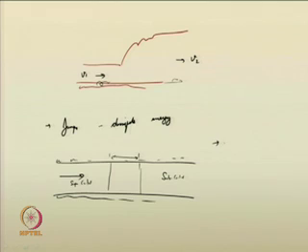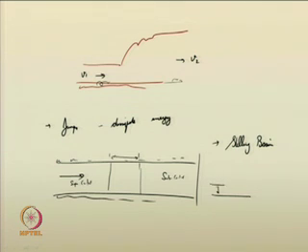The part of that reach where proper provisions for hydraulic jumps are given is called a stilling basin. If I draw the longitudinal profile, it may be something like this: a supercritical flow is coming like this and you are providing a provision in the channel bed such that from here the hydraulic jump is created and the flow goes downstream.